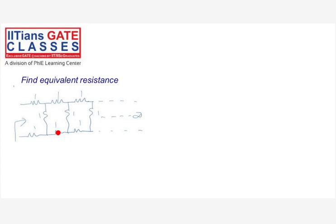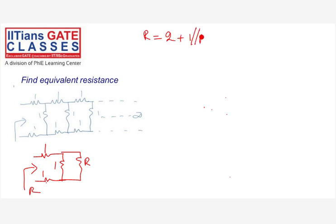So R is equal to these two in series with the parallel combination: 2 plus 1 parallel with R. So 2 plus R by 1 plus R. So R square plus R is equal to 2 plus 3R. If I bring all the R's to one side, R square minus 2R minus 2 is equal to 0.